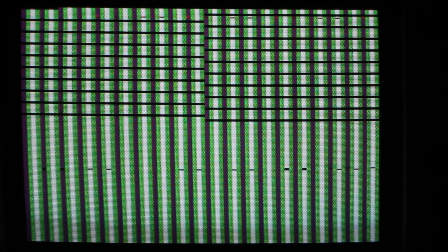Now these IBM CGA cards are absolutely notorious for this in the 80 column text mode. If you try to write to video RAM or read from it, you'll get snow all over the screen. It's usually completely random and flickery and so on. But here we've actually managed to freeze the snow in place. And we've done that by writing to video RAM in both locations and also reading from it down here in exactly the same point every frame.